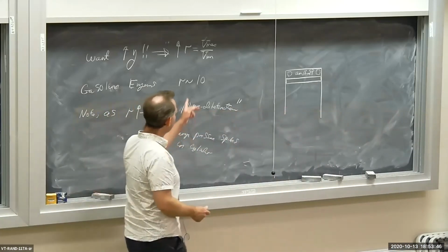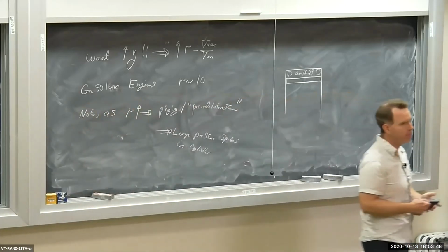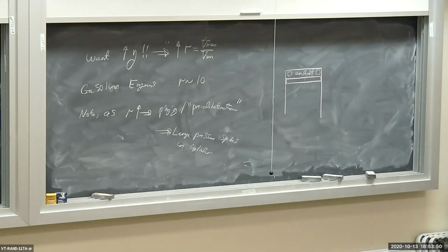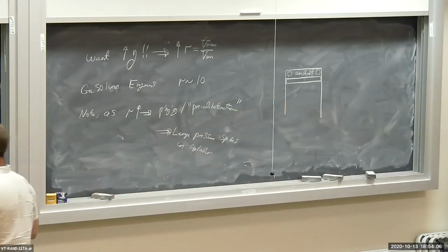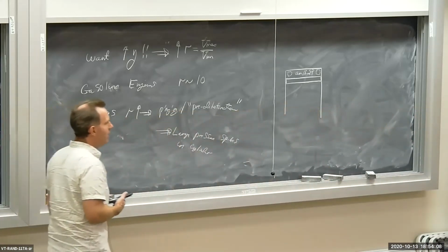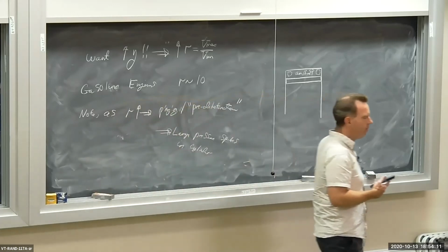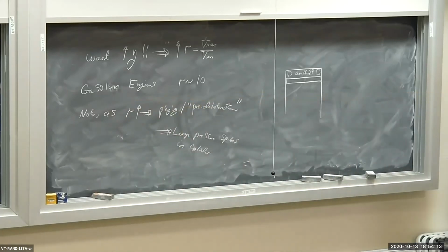So for those of you that think, well, why don't we just keep raising the compression ratio beyond 10 and get efficiencies as high as we like, there are mechanical and engineering reasons why we have not moved much beyond a compression ratio of 10. Direct injection, fuel injection, gasoline engines have helped that a little bit, but we're still stuck at around 10, 11, 12 for a compression ratio for most gasoline engines, okay?